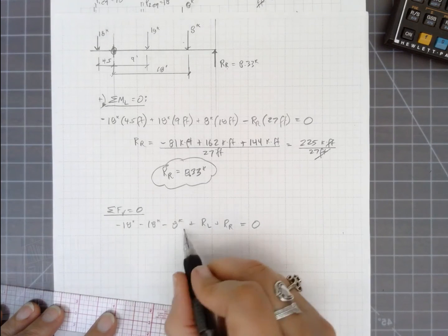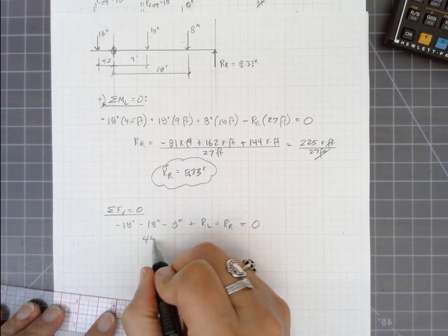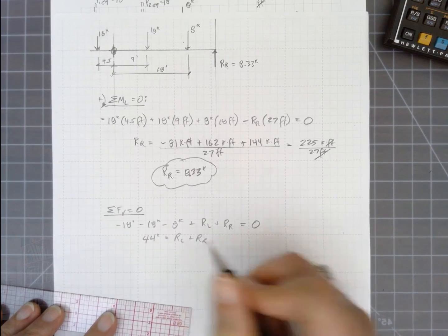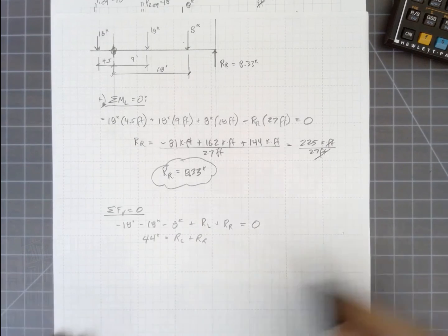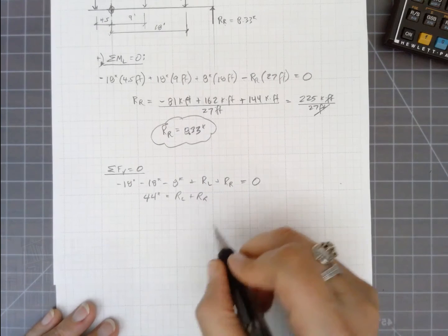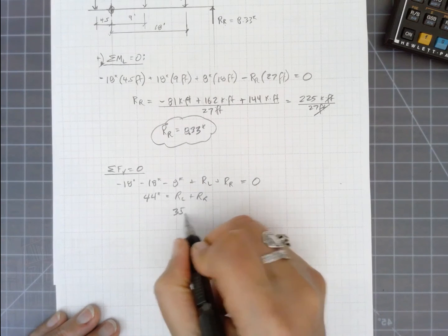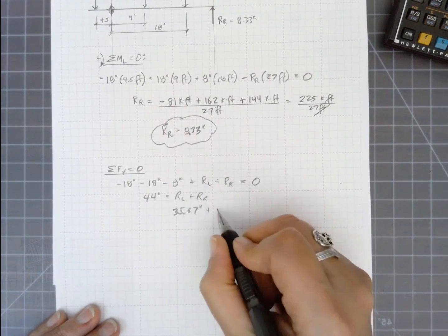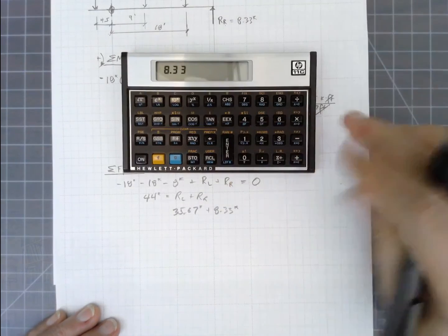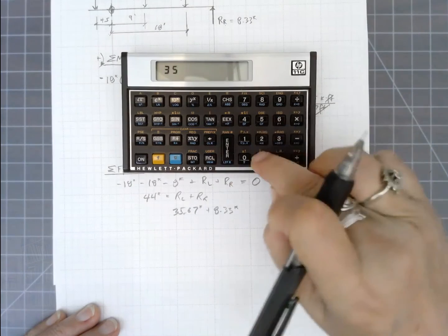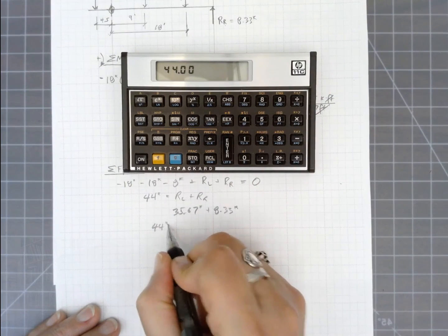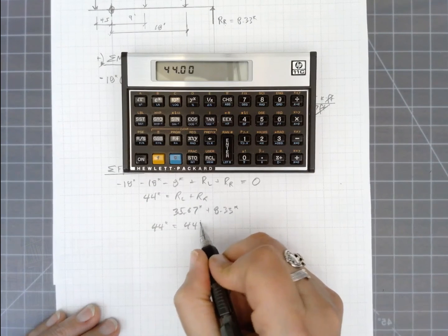So add these all up, I got 44 kips equals R left plus R right. So let's put in R left and R right previously calculated. We have 35.67 kips and 8.33 kips. And I get 44 kips equals 44 kips,